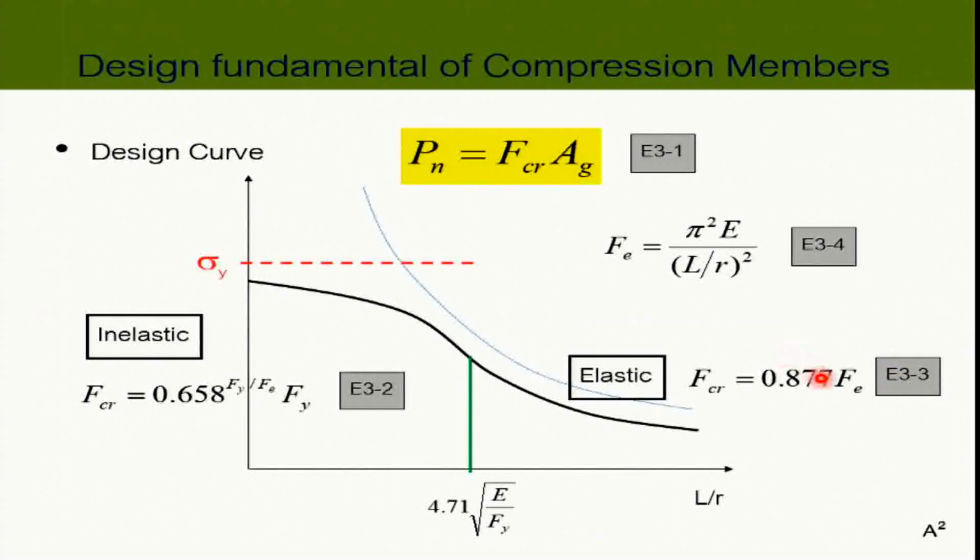Simple as that. So now, if you know the slenderness ratio of your column, you can approximate the critical buckling stress, and when you have this, you now have the nominal strength of your column or compressive member. That's simple. Okay? This is pretty much the same idea as the ASD 89 as well, but the calculation that we will use in approximation is different. I think I have that in the end of the slide, so you can just wait and see for yourself. That is the idea.